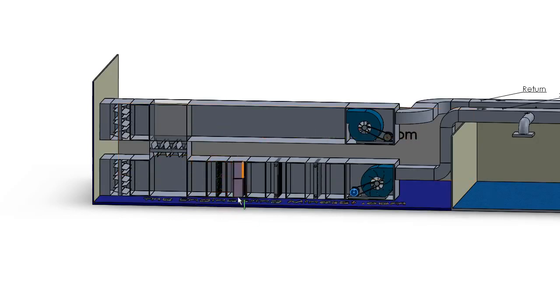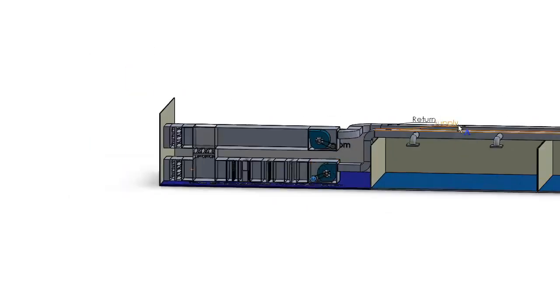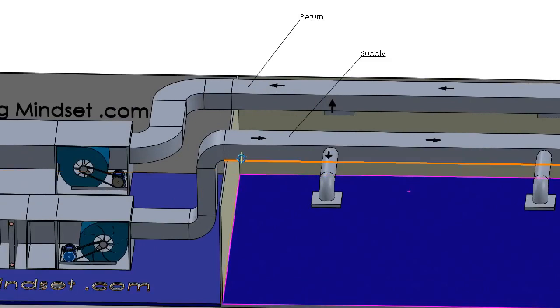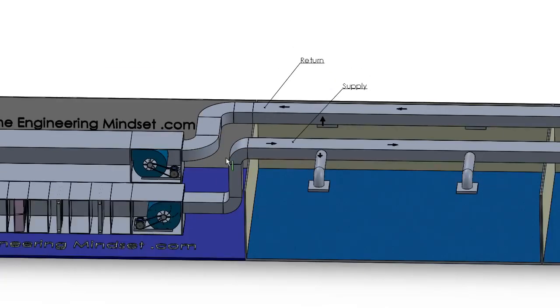Here we've got two layers of filtration protection. Then we're going to heat the air up or cool it down, maybe to change the psychrometric properties of the air. And then what's been pulling all that air this whole time is this fan, and that then drives it and sends it off into the space, into the offices, where the air is dumped. It conditions the space inside the building, keeps all the occupants happy, and then returns back through this way.